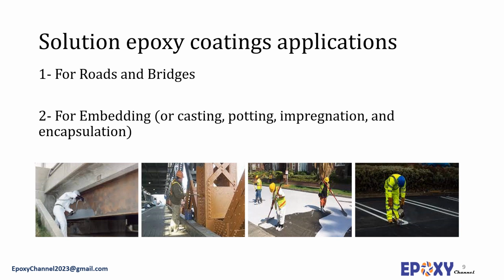Embedding or casting, potting, impregnation, and encapsulation by epoxy resins is a common practice to protect electrical or electronic devices. Protective functions such as exclusion of moisture, oxygen, salt spray, solvents, other chemicals, and microorganisms can be provided by embedding protective epoxy coatings. To protect the device from mechanical shocks and vibrations, epoxy encapsulation can be applied. Bisphenol A resins and their mixture with Novolac can be used for potting.